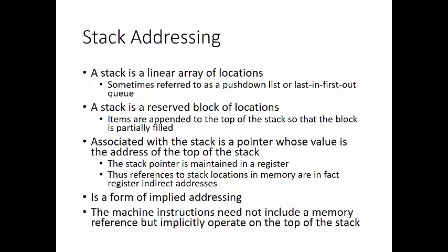So, just like you do with data structures, you have the pointer to the top. Stack pointer is maintained in the register, and references to stack locations in memory are in fact register indirect addresses. It's a form of implied addressing. The machine instructions need not include a memory reference, but implicitly operate on the top of the stack.